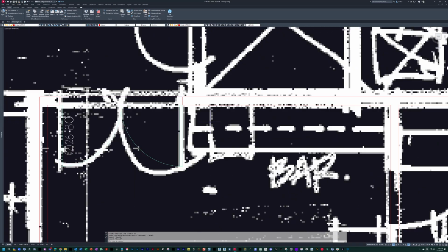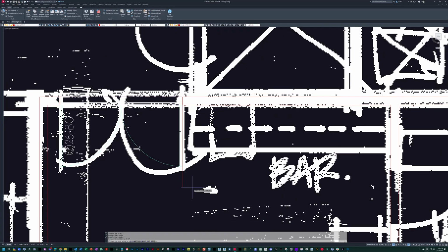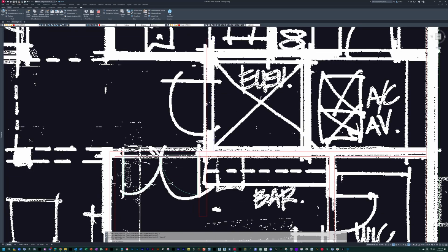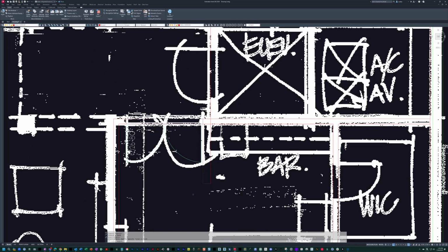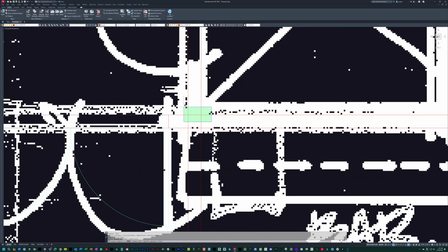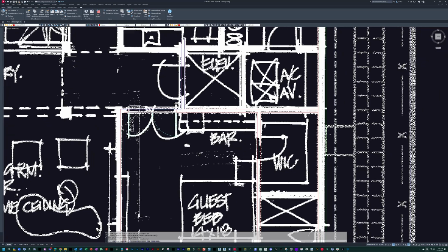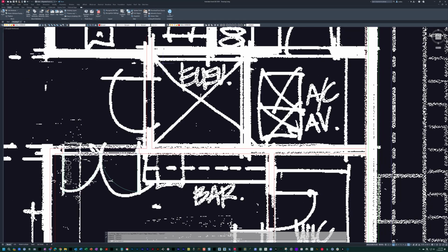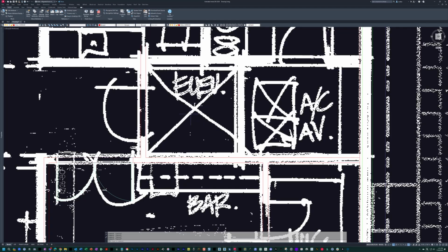So from there, similarly, I'm going to draw just a reference line 6 inches out and then up. I know that this is now going to be 6 inches to give me room for framing there. So that's good. I'm going to offset this 4 inches, and this is going to give me my elevator wall, which is good. So already getting that out. And I believe this is a 6 foot by 6 foot square for the elevator, which is nice. Offset 72 inches. And I'm actually going to offset this 8 inches on the back side.